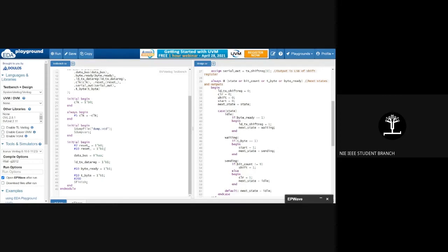And now the shift register gets completely loaded with ones. We are also doing that somewhere. All ones. See, if reset is high, when I do this, bit count should go to 0 because I'm starting from the beginning, and the shift register gets flushed with all ones. It means there's nothing. That's how we name it here. And since it's all stop bits, when it pulls down to 0, then the transition starts again. So that's how it goes.